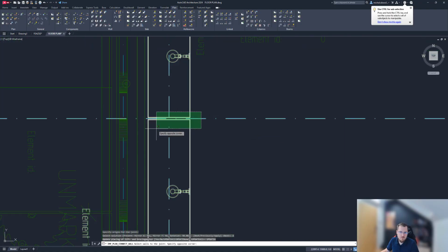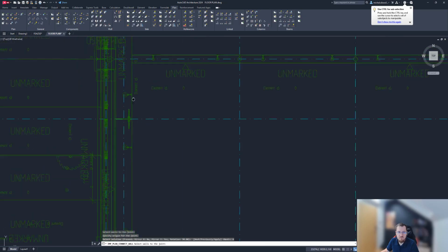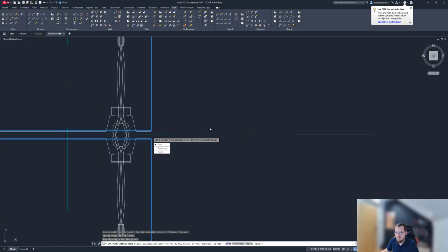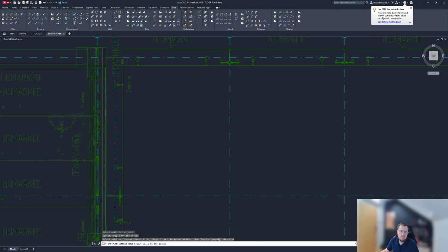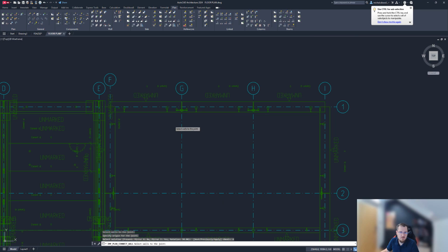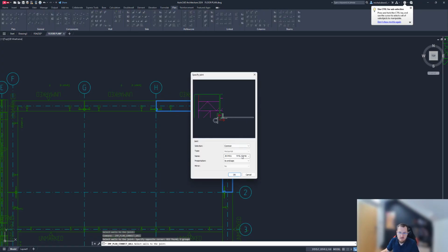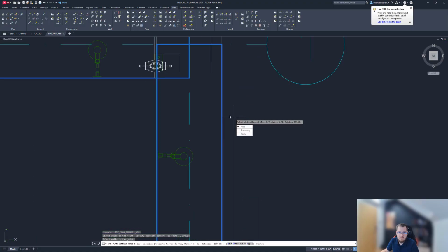And this one, of course, you can follow along and do. As you see, you are getting a preview of this. Soon we'll be done. Just do some corners as well. So I'll select the corner and I'll just select the wire loops as well, assign that, click OK, and you get a preview.